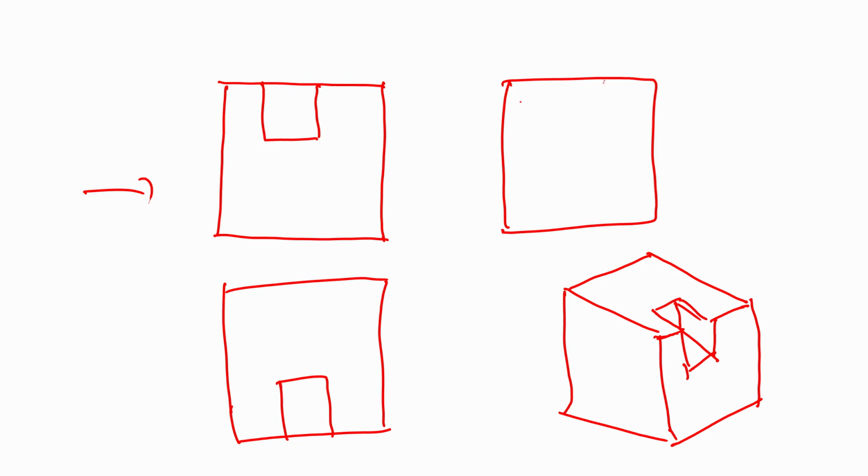So, it has been decided that you show these edges in a dotted line. Now, if I show this dotted line, you can easily imagine this object, and more than anything the dimensioning is very easy. No dimension can be repeated, no dimension needs to be interpreted.